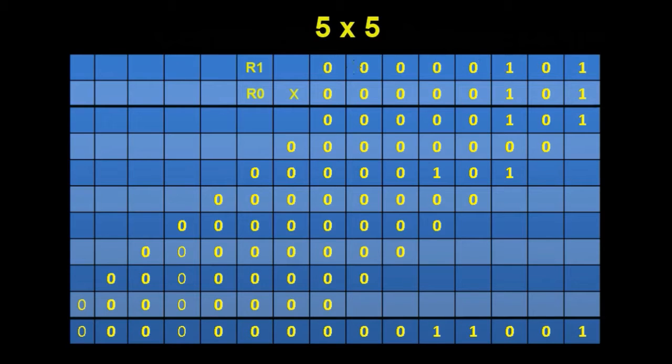So we could take the contents of R1 and just read it into another register, say R2. So we could add R1 with R2. We'd just be adding 0s, or 8 zeros, with the top line here, and we'll get this value here. Then we could shift this value R1 to the left. In effect, when we shift this to the left, we're multiplying it by 2, or we're going up by a significant bit.